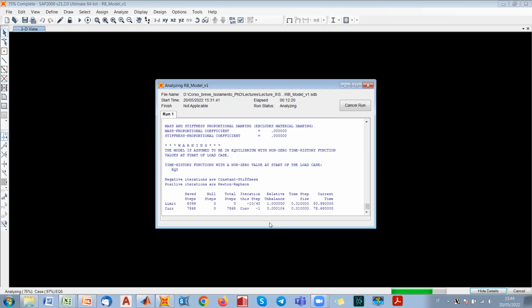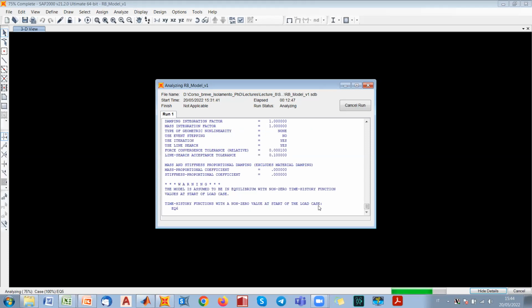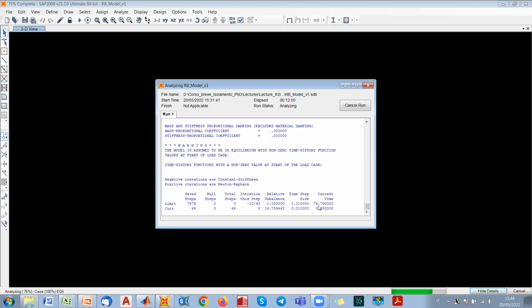Yeah, and this is an issue that we didn't apply, but this is very important. Whenever you will have ground motions with duration up to 80 seconds, this is better to be cut, just because we are considering a lot of zero paths. So these zero values for ground motion, which are actually useless. I mean, they could be useful at the end of the seismic event if we want to consider and to study some free vibrations at the end.